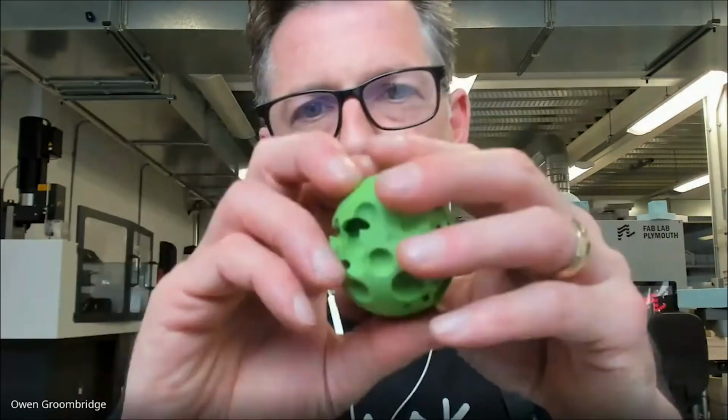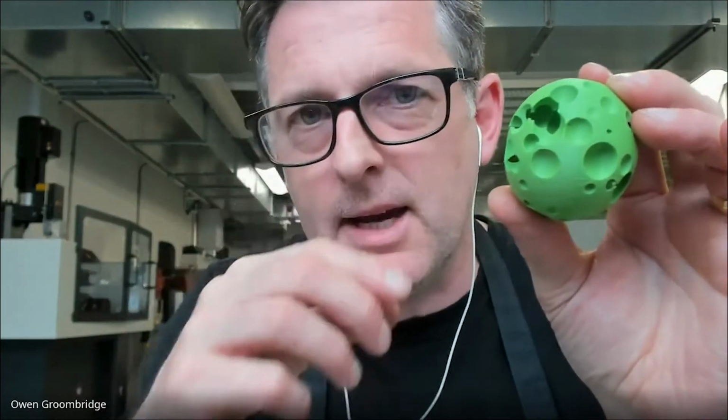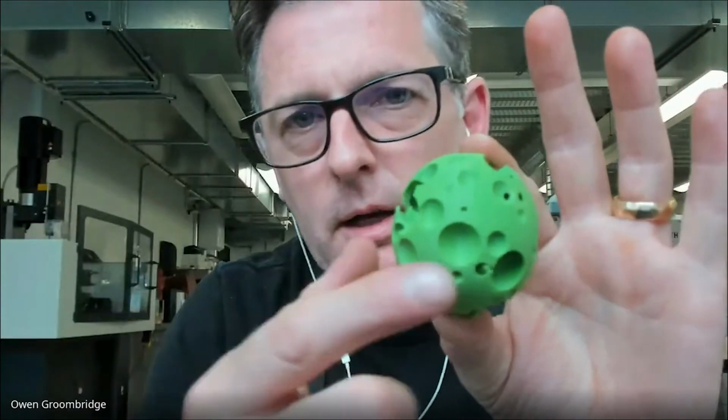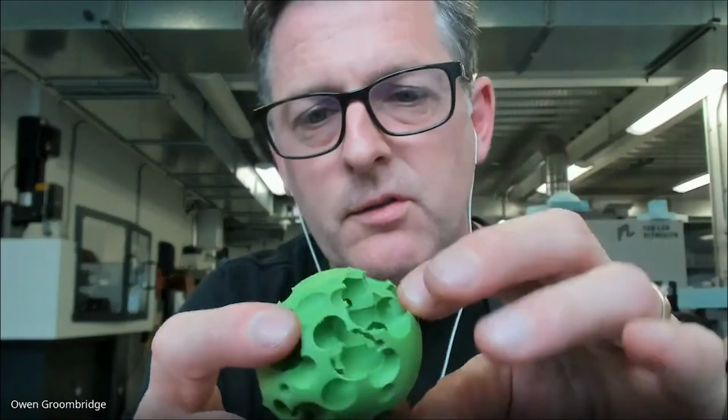Now, how do they work? Well, I've kind of told you how they work. This is basically a hot glue gun. If you haven't used a hot glue gun, fair enough, but a hot glue gun is basically a heated element and a stick of some kind of plastic or resin, and you force that through, it heats up, it melts, and it just extrudes. So this is basically a hot glue gun that goes around and around, depositing a layer of molten plastic, this PLA, polylactic acid. It's not an acid, okay?